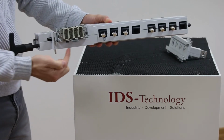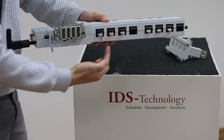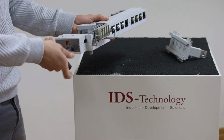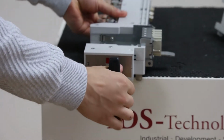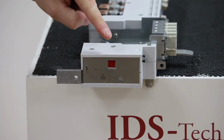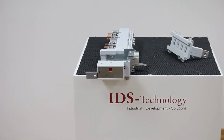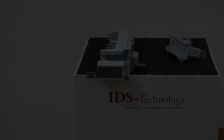As you can see here, the control plug and the contacting bolts are moved out. The window indicates fully red. The big advantage is that we can move to operate position without wrecking the drawer and without moving connected power cables.